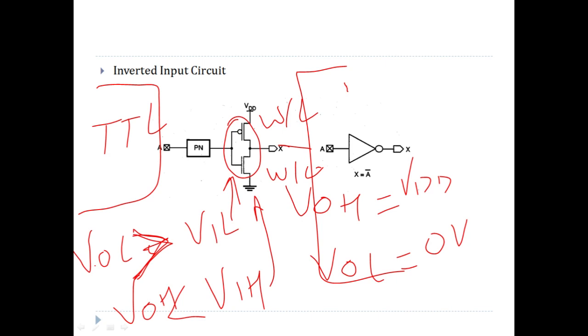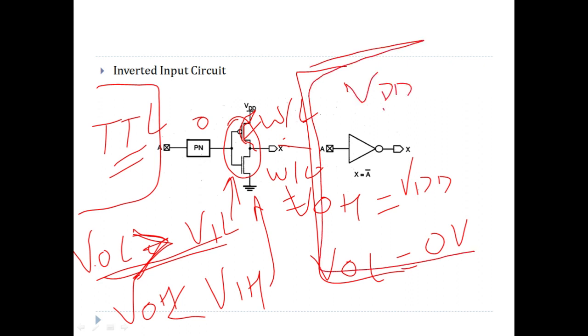So once you design it accordingly, the MOSFET operation, inverter operation, you know. So if there is logic 0, obviously this PMOS will be on, because you have to just make sure that this logic 0 is read correctly from the TTL logic, and you have to design these W by L ratios properly. So once it is logic 0, then it is interpreted as logic 0, so it will be on, and logic 1 will appear here, which is nothing but VDD, which is very much compatible with